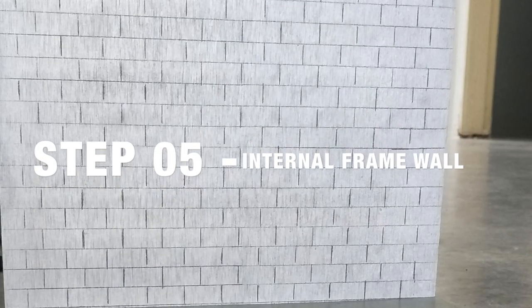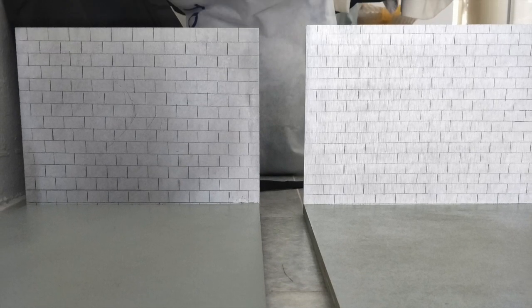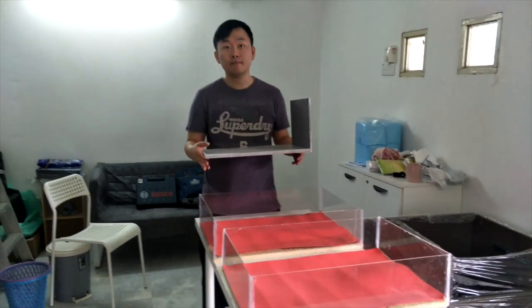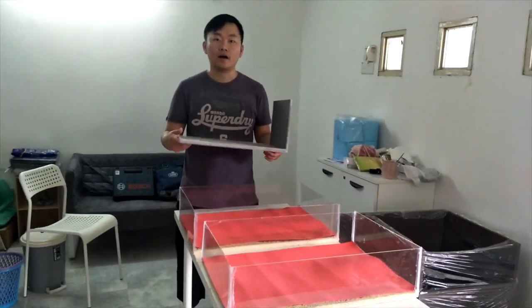Internal frame walls are usually added to divide the building into compartments or rooms. The function is to transmit floor or roof loads to a suitable foundation. Bricks are used for partition if a high standard of fire resistance is required. For load-bearing walls in single and two-story houses, the minimum thickness of the blockwork is 90 millimeters, whereas for 3 stories it is 140 millimeters. This is to ensure the strength and stability of supporting the load.